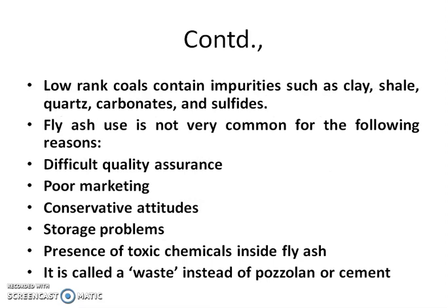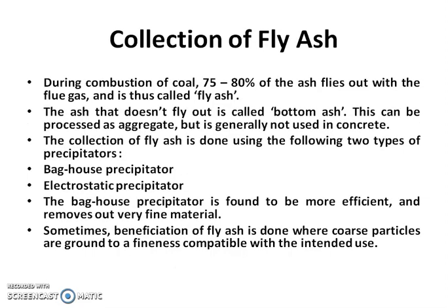So fly ash is not very common because of the following reasons: because of the poor marketing, because of the storage problem, the conservation attitude, and it contains many toxic chemicals. Moreover, we are calling it a waste instead of calling it a pozzolanic material. Now many researches are going on, and now we are taking this fly ash as a pozzolanic material.